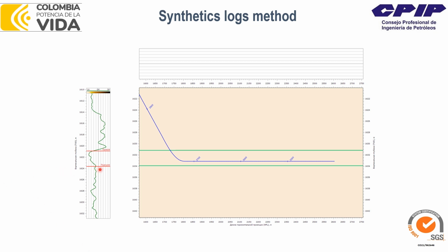Okay, so the next step here is to fill this curtain section with the formation properties, right? So we will start from the basics, from the gamma ray. Where do we take the properties? We take them from the offset well, which is the closest, most representative well we have, right? It can be a few offset wells, so we can choose between them, or we can build a few curtain sections if you want to refer to one or another depending on what's going on with the properties. So let's start from the basic.